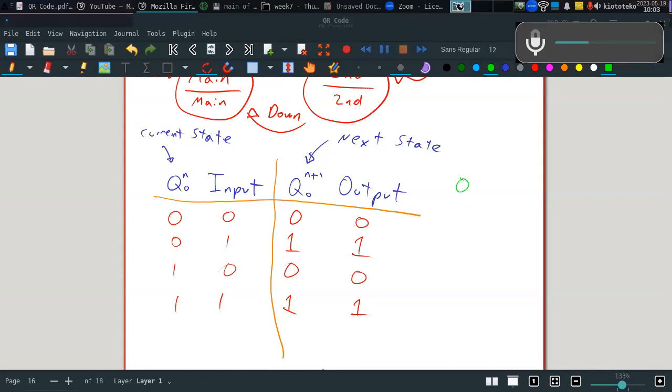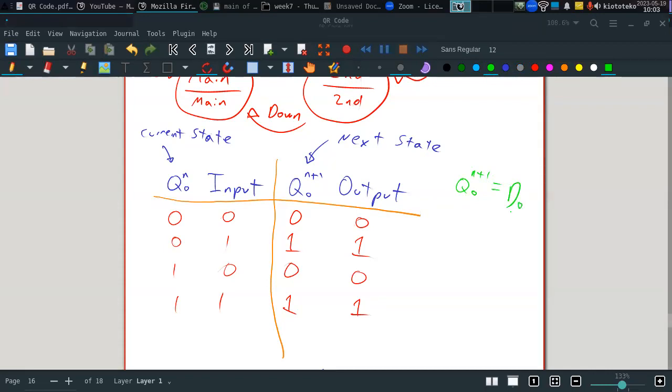So that means that the Q0 next, which is the next state, will be defined by D, no? This way we will be maintaining this state. Obviously, if we had a JK flip-flop, we would need to put the equation here, of JK. And we will need to, I guess, have the table of the JK flip-flop to see how it corresponds to this single bit input, no?